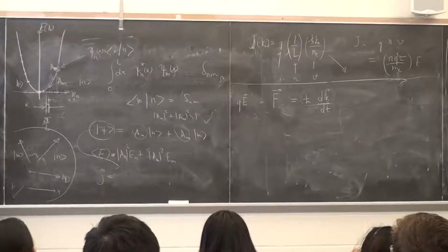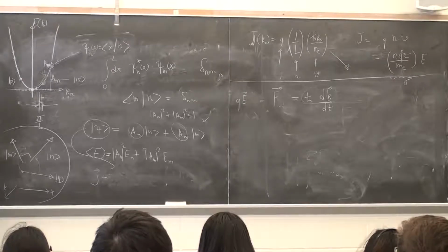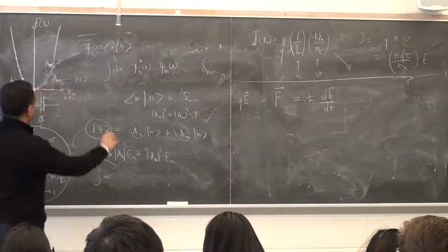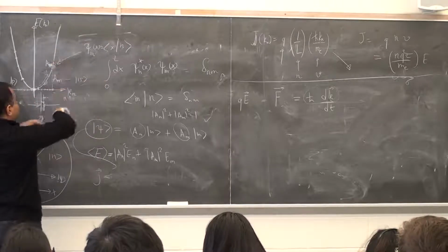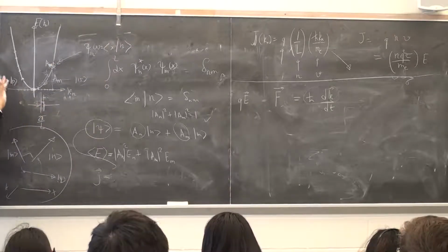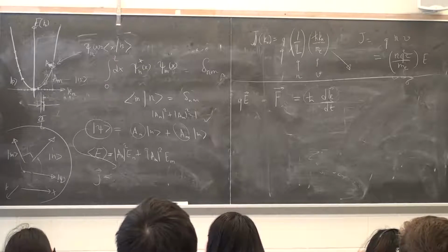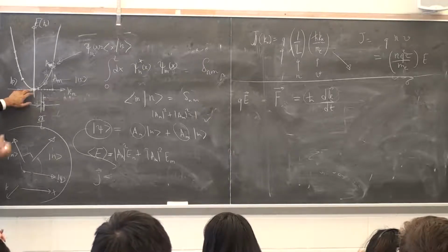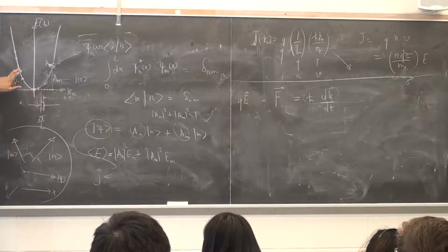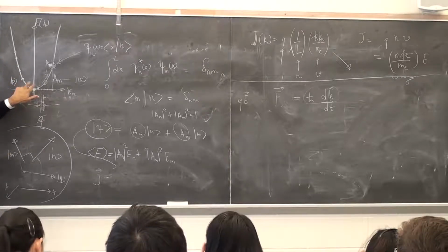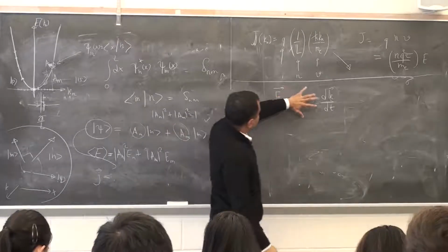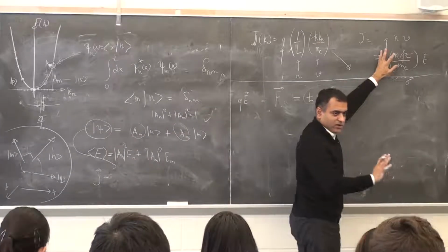Now, let's say you allow it to scatter, and we'll see later, if you let it continue, by the time it's way out of equilibrium, it has a lot of energy and a lot of chance to scatter. If you can collect it with no scattering at all, that's called ballistic transport. It just goes from one contact to another with no scattering. But we want to relate it to the Drude model, where we allow a lot of scattering.